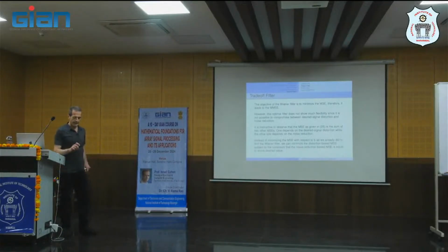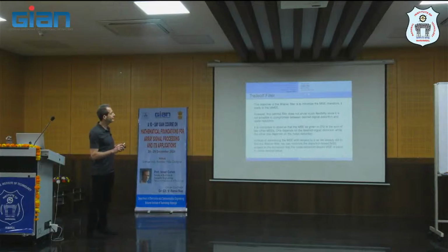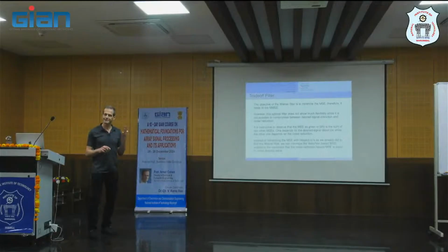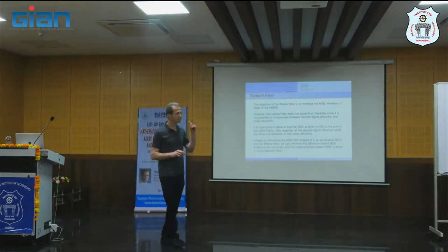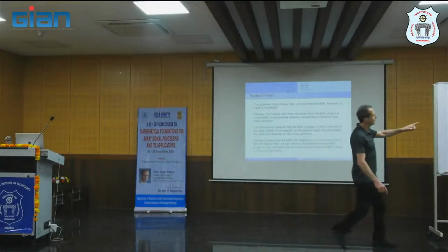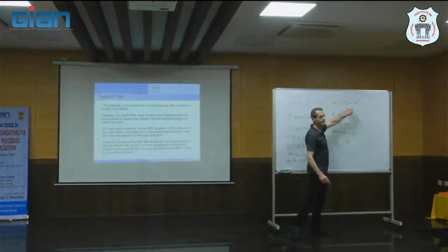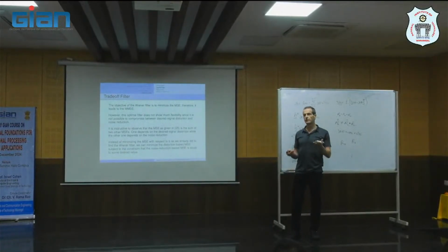Okay. And afterwards, we will talk about different filters, which are also important. We will talk about the trade-off filter, MVDR, and the maximum SNR filter. The trade-off filter, we will see, because if we try to minimize the mean squared error, actually we minimize both the distortion and the residual noise. But sometimes we want to reduce more distortion at the expense of increasing the residual noise, and vice versa.